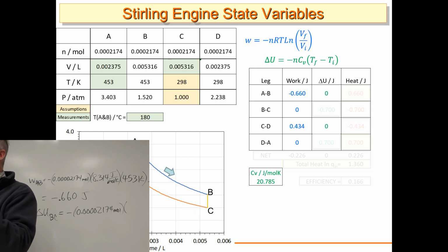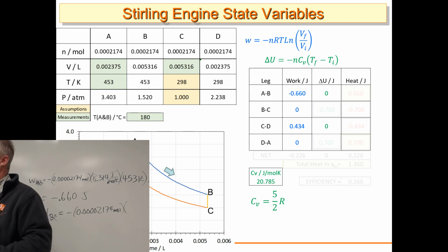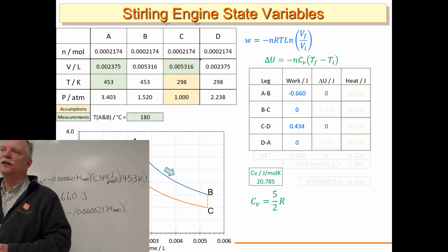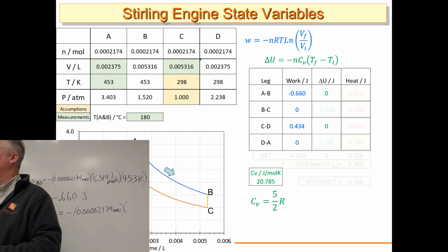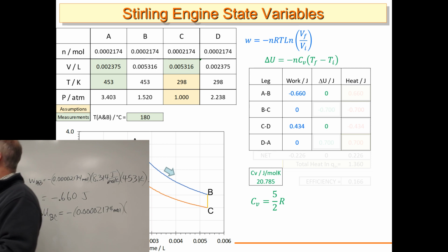Okay. So we have translational degrees of freedom, and we have rotational degrees of freedom, and we're not going to have any active vibrations because we're not at a hot enough temperature. So we can just treat atmospheric gases, even though they're different species, nitrogen, oxygen, CO2, as a linear working fluid. So we would have CV is 5 halves R. We have 3 halves R for the translations and another 2 halves for the 2 rotations. Because it's linear, it only has 2 rotational degrees of freedom. So that would be CV, 5 halves R.